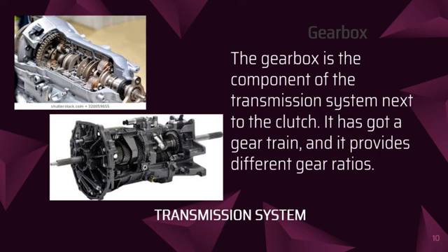The torque transmitted to the road wheels gives rise to the propulsive force or tractive effort between these and the road. When starting from rest, a large tractive effort is required. This makes essential the introduction of considerable leverage between the engine and the wheels so that the torque from the engine, which is almost constant, produces the large tractive effort.